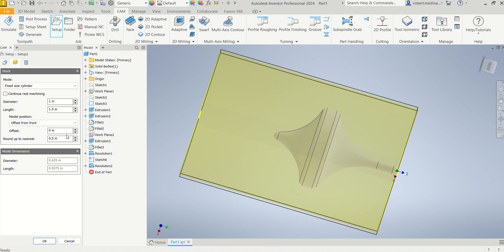It's more for if you got a piece of material that was cut really roughly, you might want to offset it maybe 0.1 just to make sure that you have a nice clean finish here. Get rid of any of that rough surface from a saw cut or something like that.